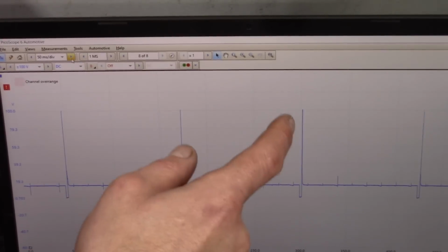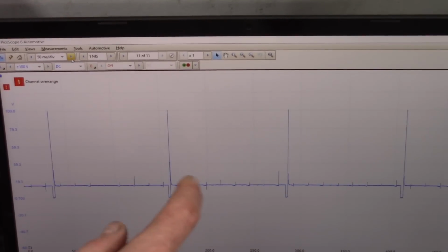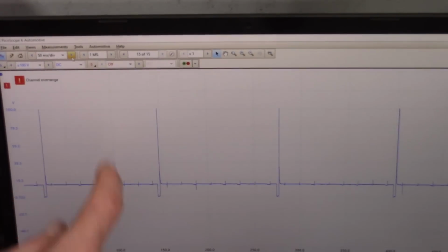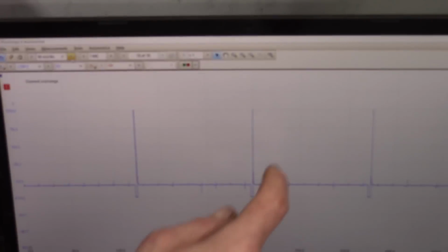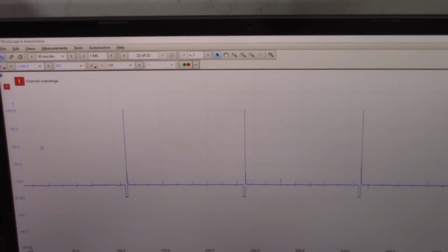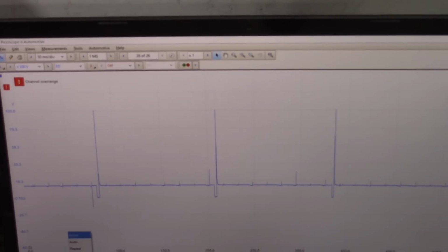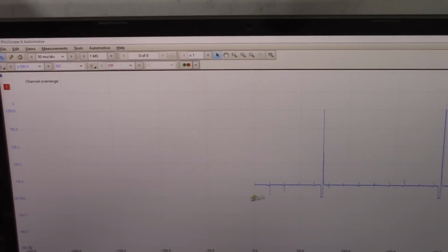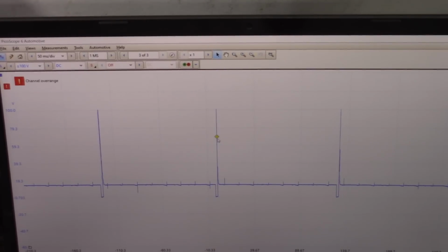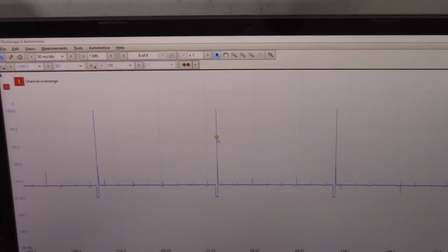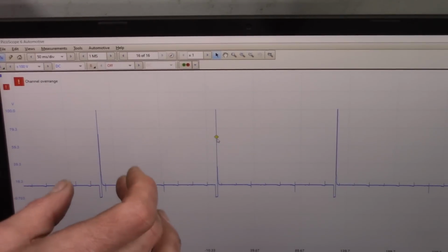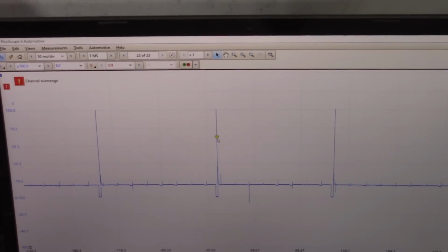That's an injector turning on and off, on and off, on and off. You see the on time is very minimal. All off time, then it's on again. We can trigger this. All right, so we don't get exactly a square wave here, again, because of the effect of the solenoid. But if we expand this out,